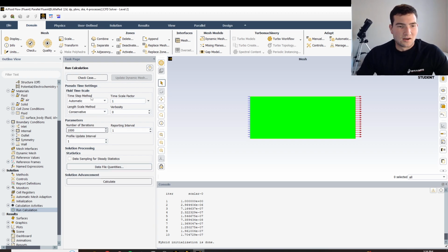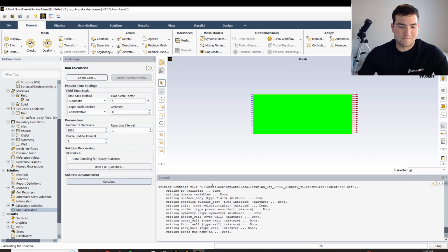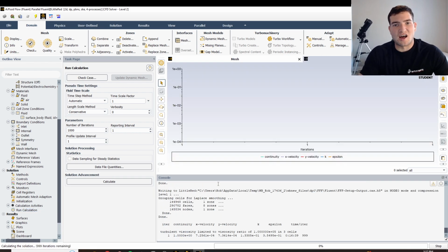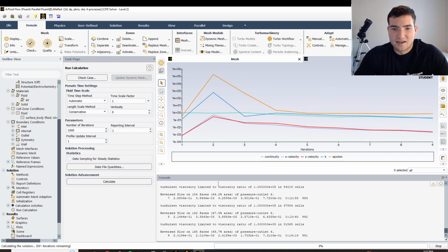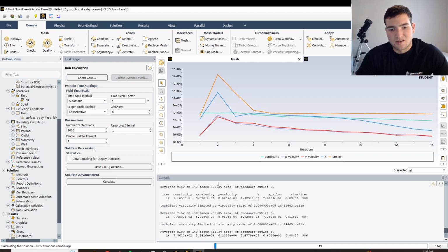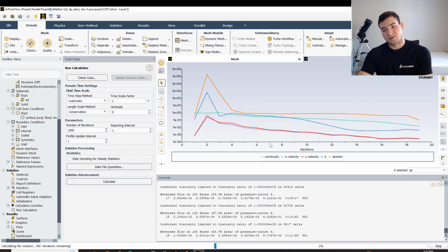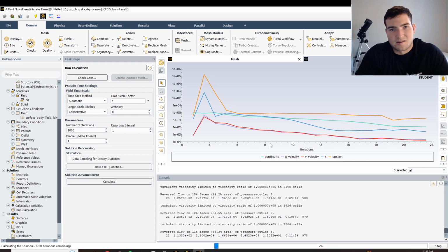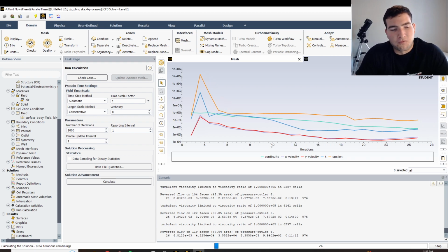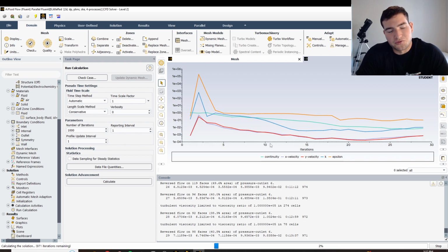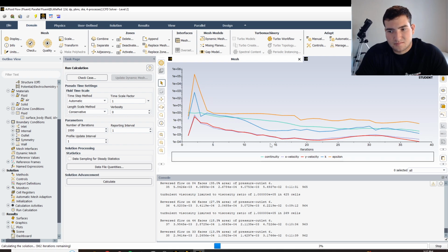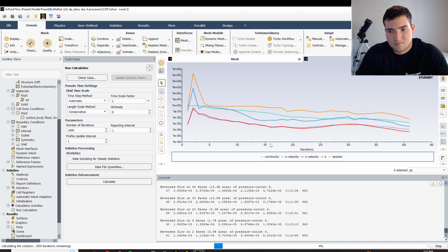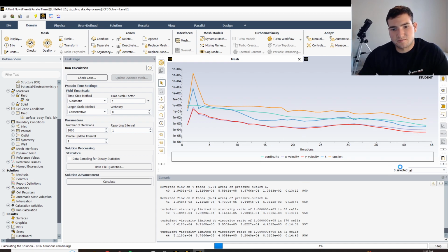For the number of iterations we'll do 1,000. Probably not going to need 1,000. It's going to say the mesh did not converge in a certain number of iterations or something like that. What we're looking for right now is convergence as well. So it shouldn't take 1,000 to converge. It should converge earlier, and it should tell us that. It can range from like 40 iterations to 500. I've had it do 500 and still converge. But right now it's looking pretty good for convergence.